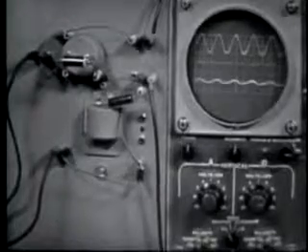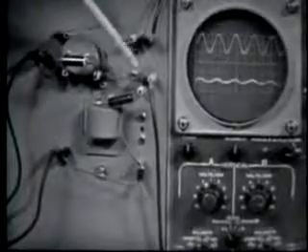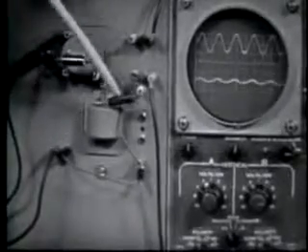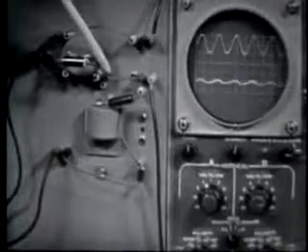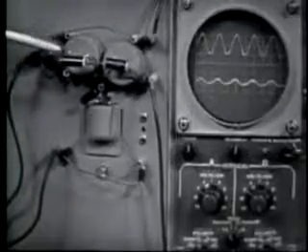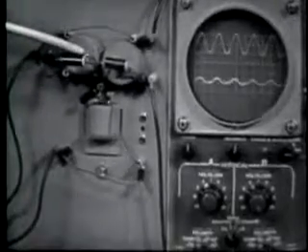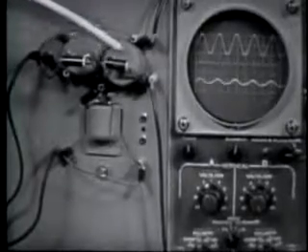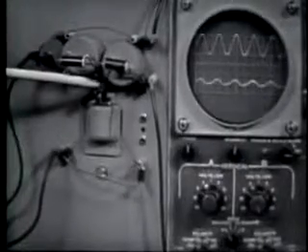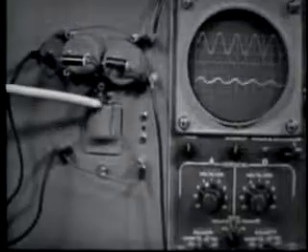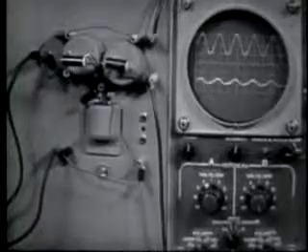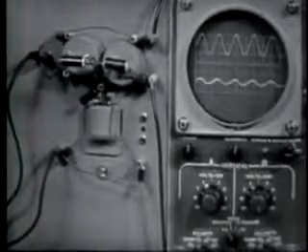So let's make a T section from this basic L section and see if we can improve the frequency response. Now to make the T section we'll need another parallel tank in the output leg of the series position, and we'll need to move our series tank over to the junction between the 2 parallel tanks. Now let's do this. Okay, parallel tank here in the input series leg of the filter and a parallel tank in the output series leg of the filter. And our series tank now is connected from the junction of these 2 tanks down through the capacitor, the inductor in series, and down to ground. So we have a T section band reject filter.